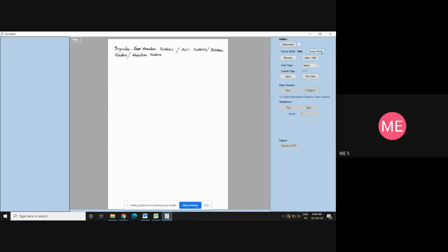This is the first formula we'll use. U mean, that is the mean speed of the rotor, is equal to pi d mean N by 60, meter per second. You observe here d mean, because this is very important. For example, in some problem he will give diameter 1 and diameter 2.